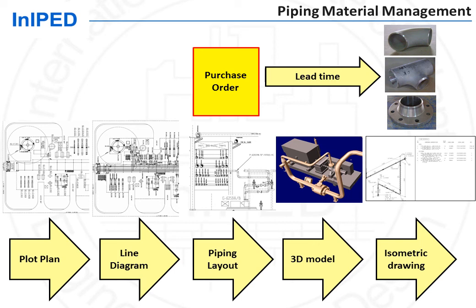Such bill of materials will be done from the second revision of the P&IDs, the issued for design P&IDs, which is not the final issued for construction revision, and from the piping layout drawings, because the piping isometric drawings are not available.